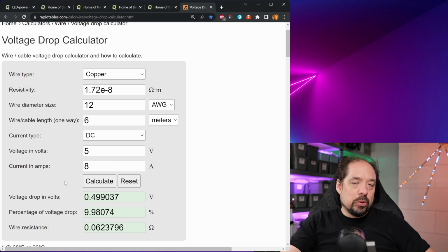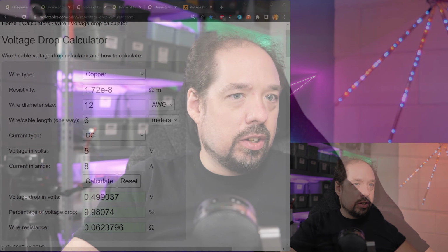Because the problem with 5 volt LEDs is basically, if you compare this with PoE or other standards, those are all devices where you have an input voltage and the output voltage is converted again at the end. So for instance, with PoE, you input 48 volt and at the end 35 volts arrives. That's not a problem with PoE because the end device converts that 35, 38, 40, 42 volts, whatever is coming in, down to, for instance, 12 volt, which it needs itself, like an IP camera or something like that. So it always down converts.